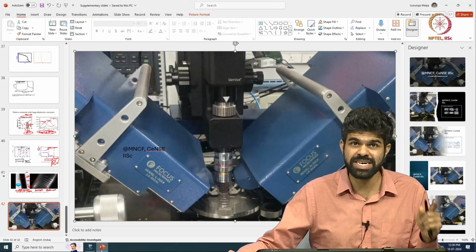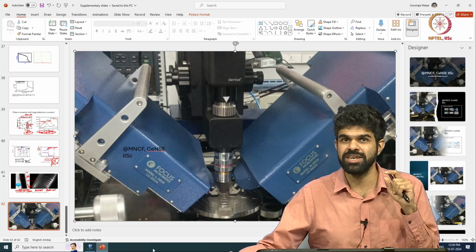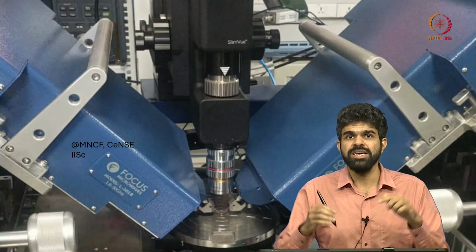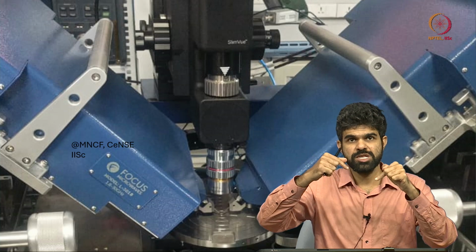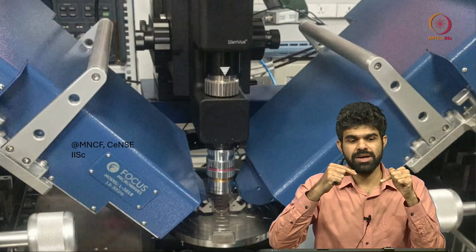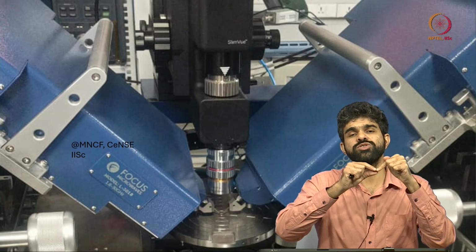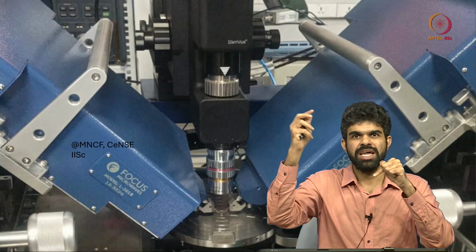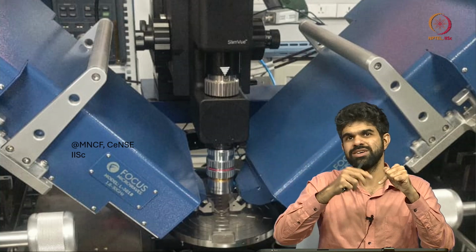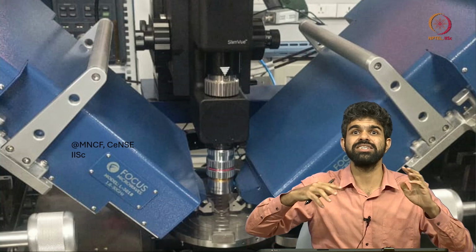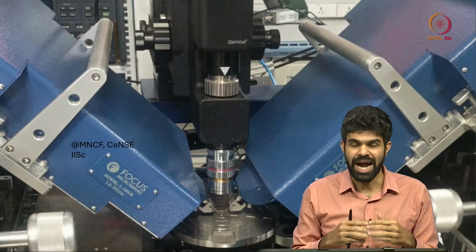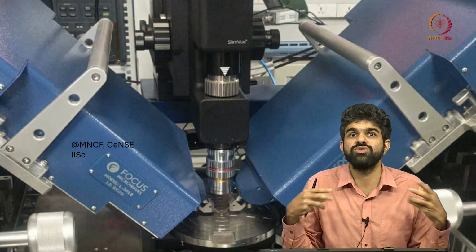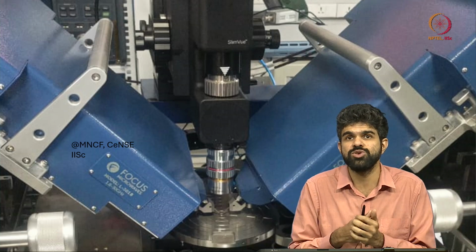You can still do it electrically, but then you have to be very careful. What care are you going to take, right? Essentially, if you have probes, these probes also act as inductors, right? So they can gather some electromagnetic radiation from outside, and they can add some additional elements that are not present in your material. So you can have contact issues, you can have probe issues and other things, right.